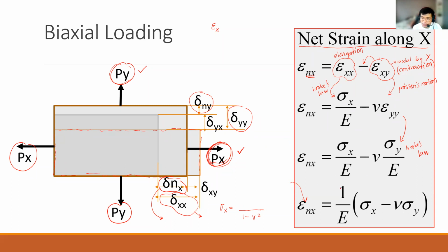So if you try to rearrange the formula and you're looking for the stress part of the problem, there's a manipulation of this one. You use that manipulation method in your problem. And then what will happen is the sigma sub x will become isolated, and there's a new format for the equation. I think it's this one: epsilon sub x minus nu epsilon sub y, then multiplied by E. So I think that's the other version of this formula.